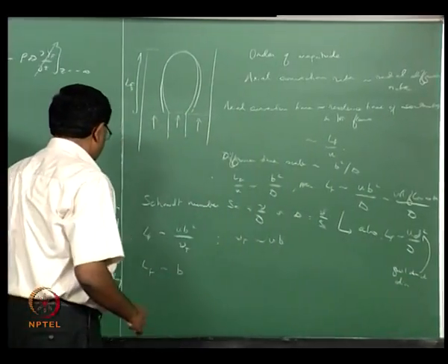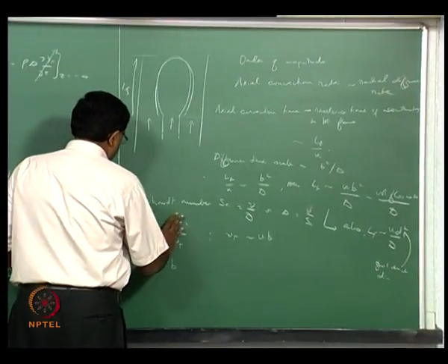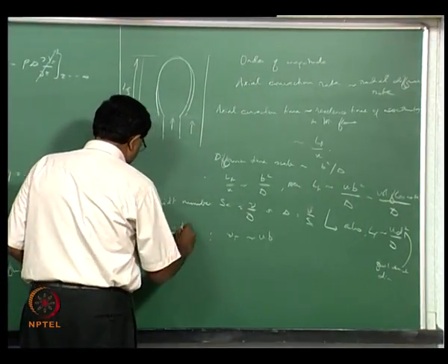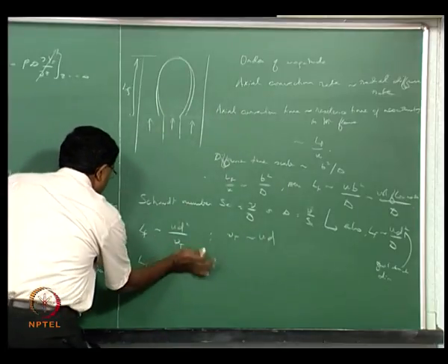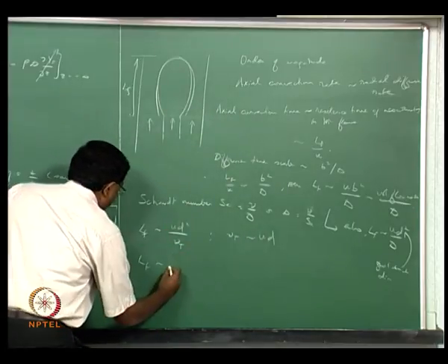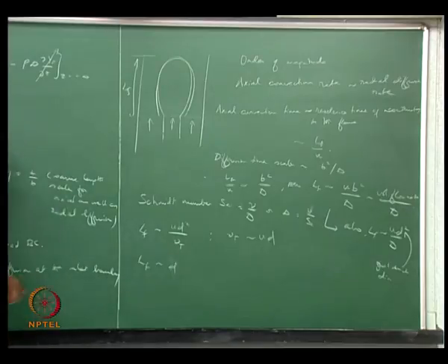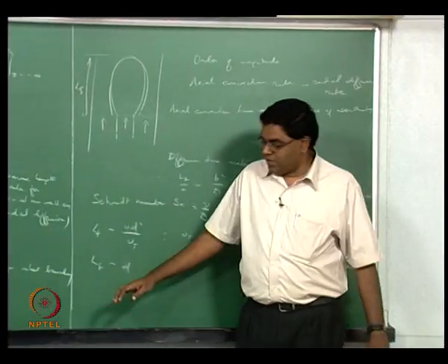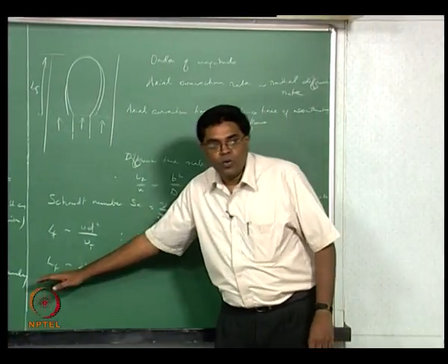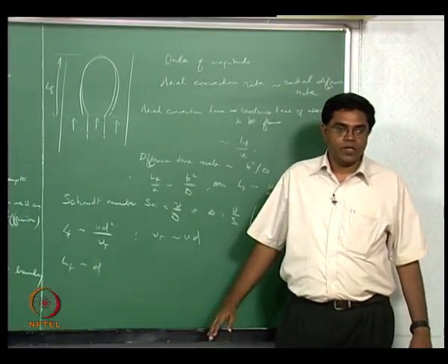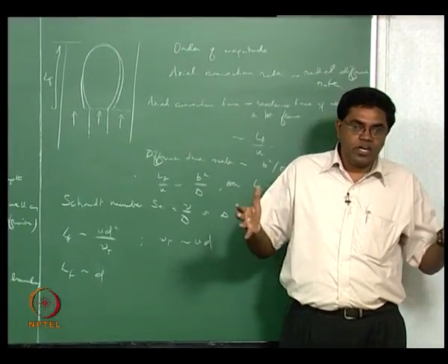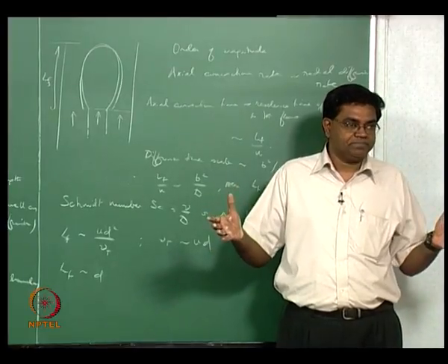It makes a lot of sense to talk about it this way in the context of jet flames, and keep it as d rather than b, because I'm no longer thinking about the outer duct diameter, but mainly the fuel duct diameter. So what this tells us is the flame length is no longer going to be dependent on the flow velocity. It simply is going to scale only with the duct diameter.